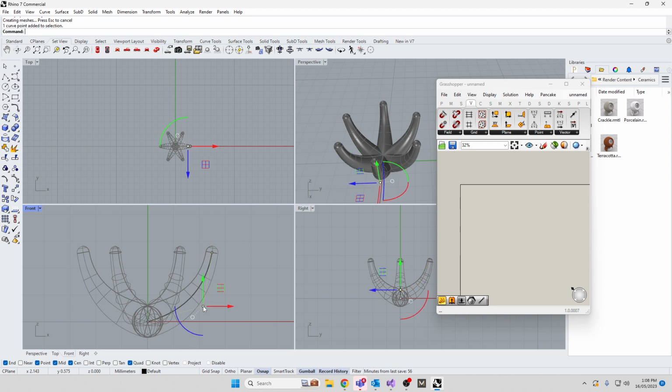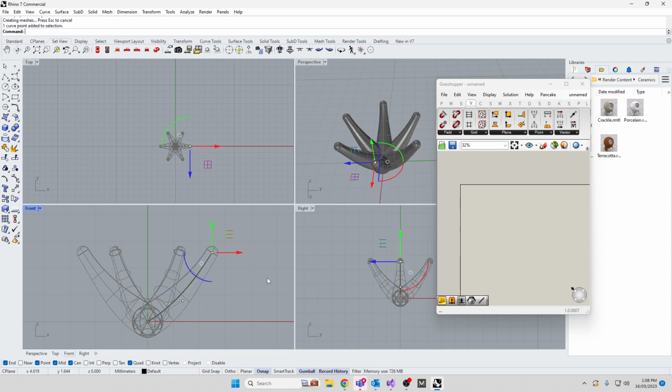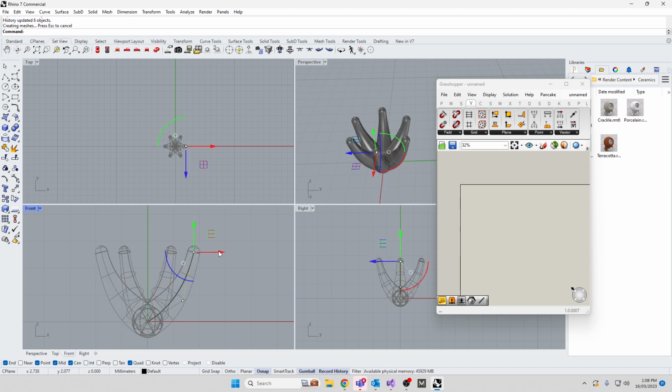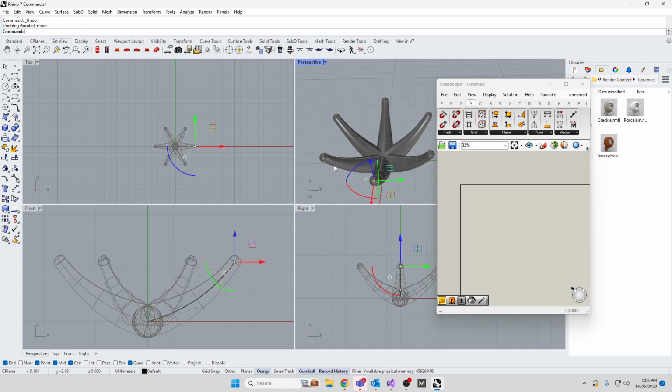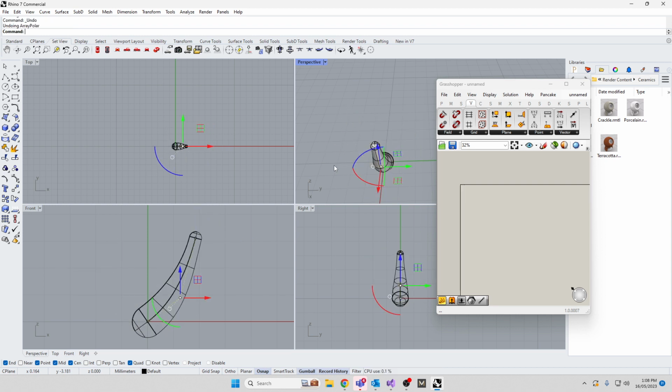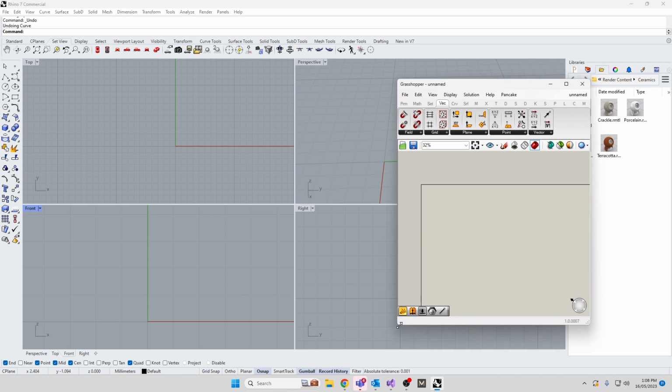So there are times and places where you would jump to Grasshopper to produce a few constructs. Okay, so I'm going to hop out of here. Let's get rid of all that stuff we did, and get rid of the curve. And let's talk about how we do the same thing in Grasshopper that gives us a better outcome. We're going to start off the same way we drew that curve. We had a point and a point and a point, and then we drew a line through them. In my case, I'm going to use an arc.